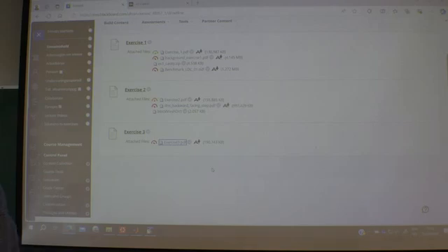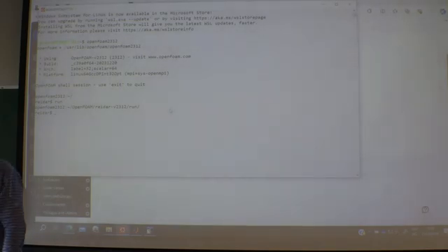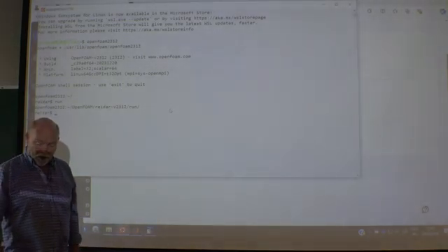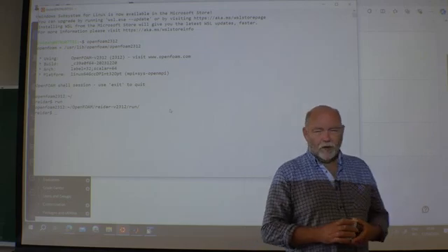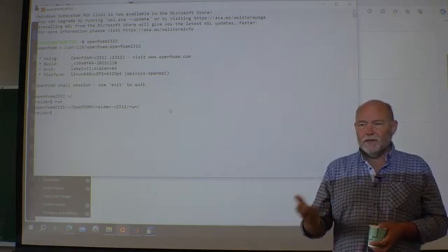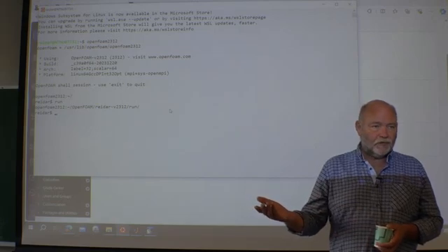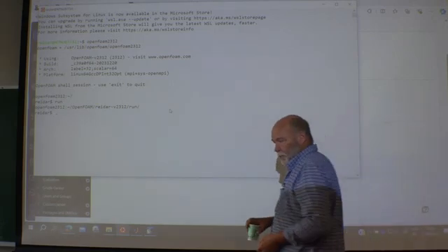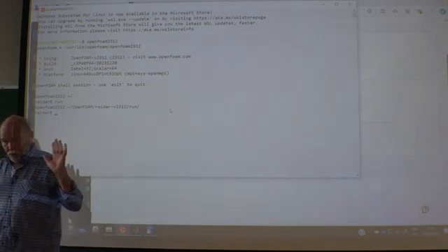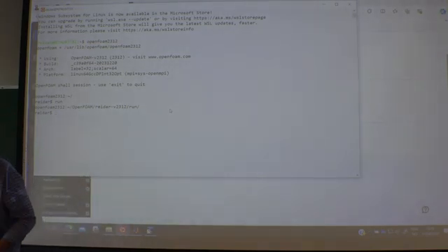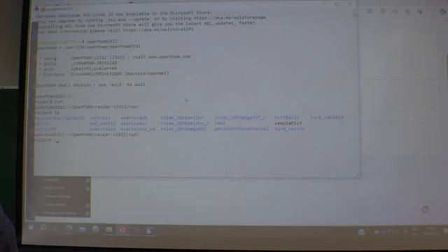Then let us jump to OpenFOAM, and I want to sort of extract the data from an OpenFOAM case. I'm going to need this data because I want to now make some nice plots in, for instance, MATLAB, Python, GNU plot, whatever you want. But I mean, you need the data and how to achieve it. So as a first test here, let's use the cavity case.